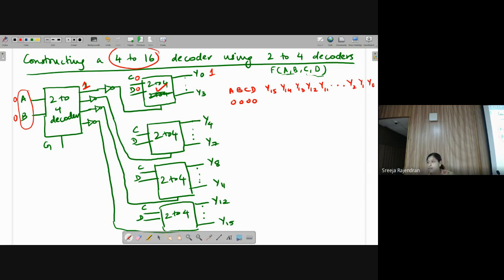Inverter goes 0, right? What is G supposed to be to activate a decoder? What is the value of G? G should be 0. Only then the module is activated. So since the design is like that, if any of them turn 1, nothing is going to be activated. None of my decoder blocks in the next stage is activated. So I have to invert it after that.